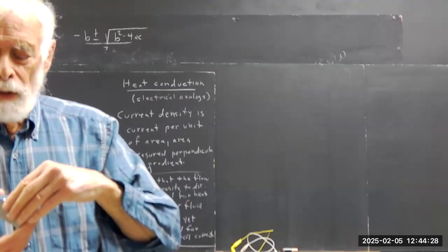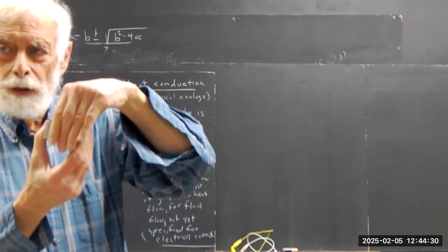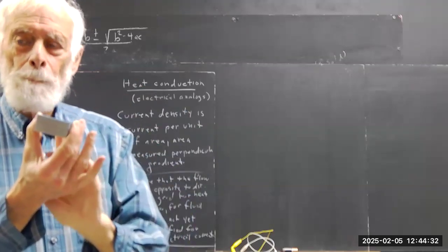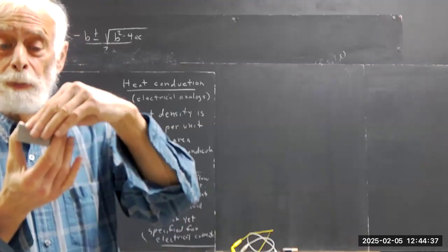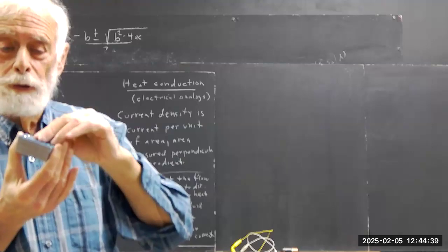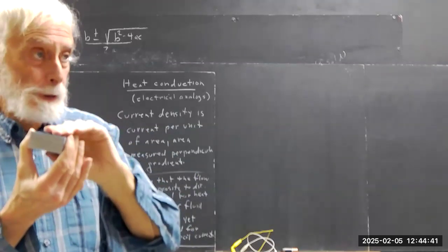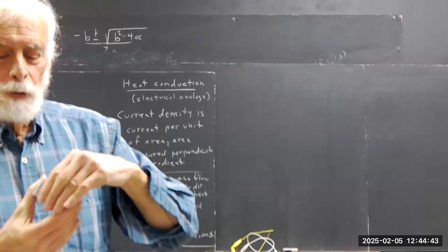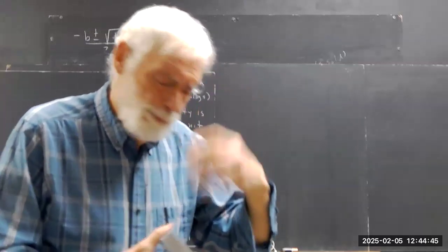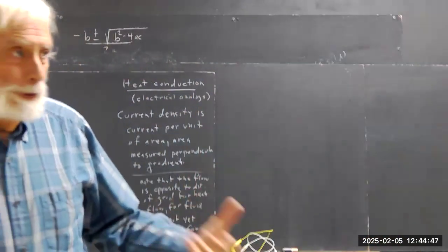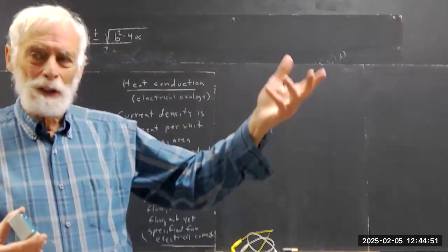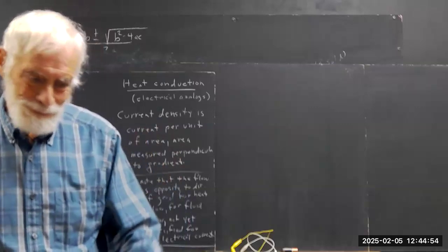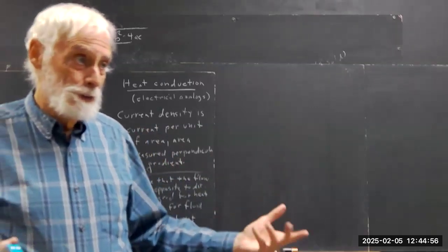So in other words, cross-sectional area here is measured perpendicular to the heat flow. Heat flows this way, and these plates are perpendicular to the heat flow, or the heat flow is perpendicular to the plates. And that's pretty intuitively obvious. We can set up the diffusion equation and solve it with a partial differential equation, and we're not doing that in a simple calculus 1 based physics course.